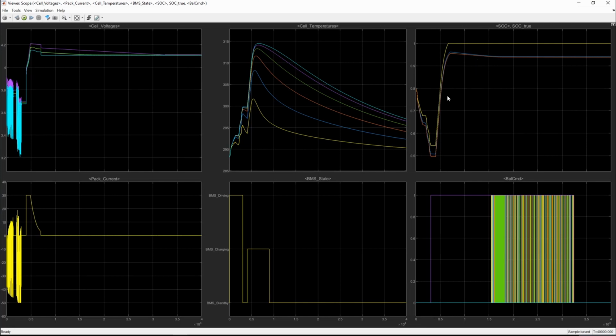The initial SOC in this simulation is 75%, but the SOC estimators were initialized to 80% in order to assess their capability to recover. It is apparent that Coulomb counting never does, because it has no way to realize it is wrong due to the absence of voltage information.